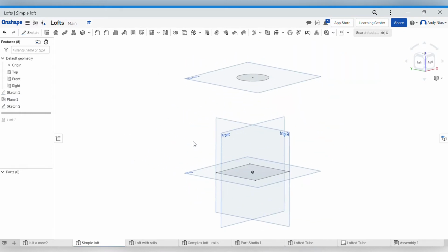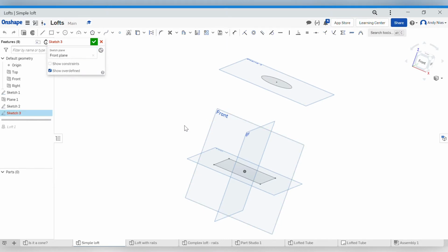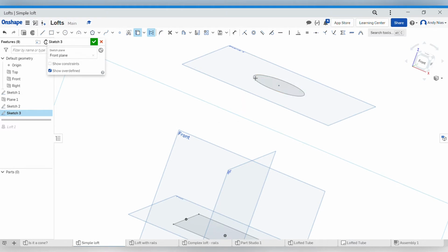So I've just got sketches now. Let's go for a sketch on the front plane. Now I want to make sure it runs right through these two sketches, so I need to project the point. That one there, I'm going to project the midpoint or the point of that line, so I know my sketch starts there. It's going to hit that line. This top edge is a curve. I've not got a point, but if I project the whole line, then I'll get two spots.